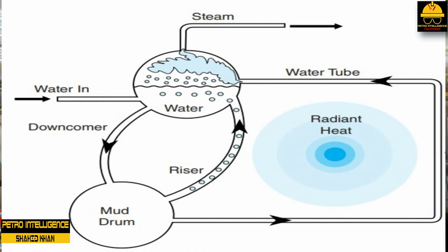Hot gases flow out of the firebox, into the economizer section, and out the stack. Water temperature increases at programmed rates. Pressure begins to increase. Steam may initially be vented to the atmosphere. As the temperature of the water inside the generating and riser tubes increases, the density of the water decreases and initial circulation is established. Bubbles begin to form and rise in the water, increasing circulation and pressure as shown in picture.